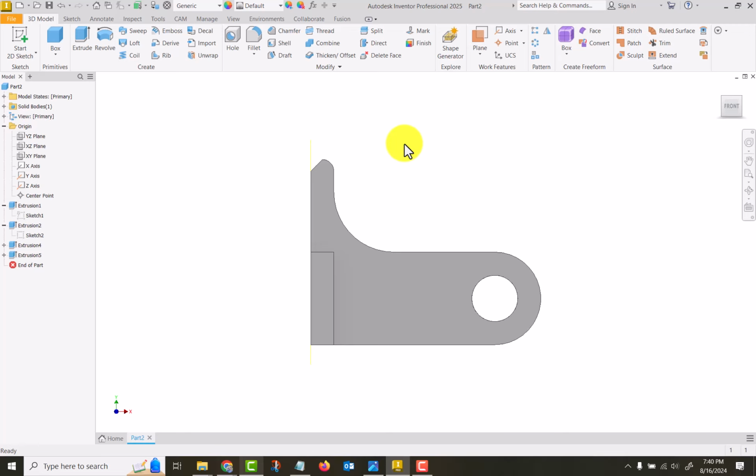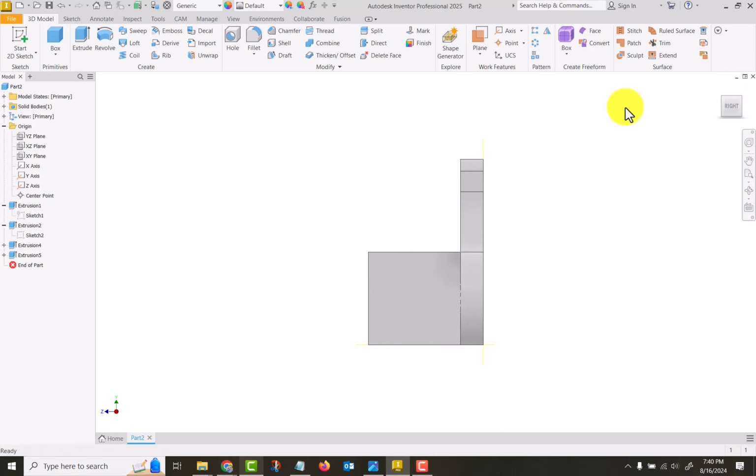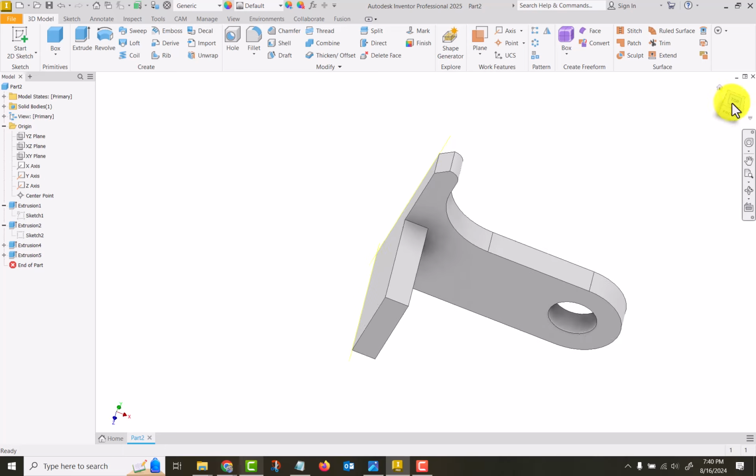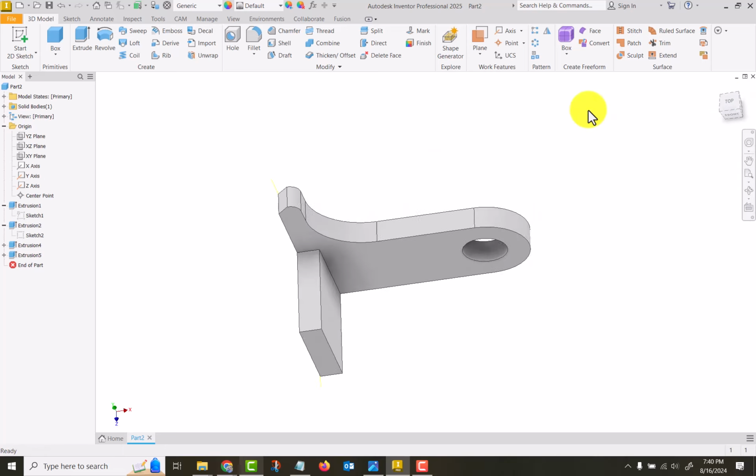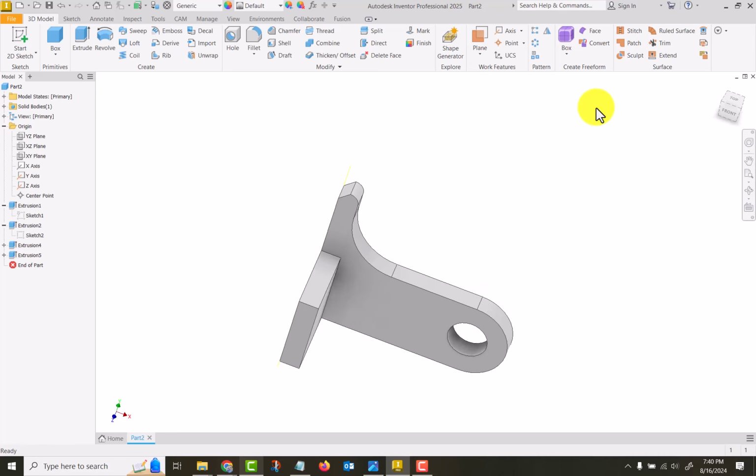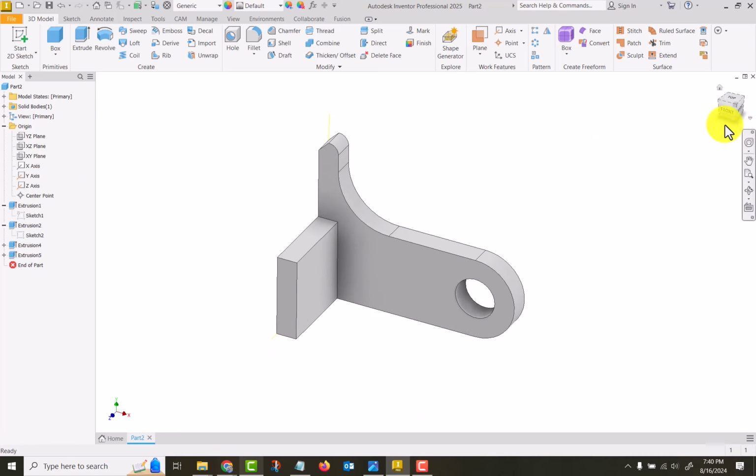But think about what surface plane you want to start with, because when you go to place it into a drawing, this front is the front view of your drawing. It makes it easier. And that is the right view of your drawing. That's the top view of your drawing. Now we can change those around in a drawing, but it sure makes it simpler if you keep it correctly here in your model. Okay, so I think that covers most everything you're going to need to get you used to using the software this week.